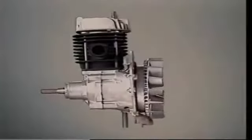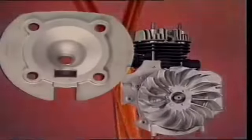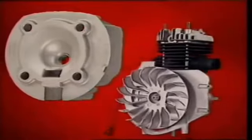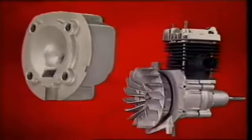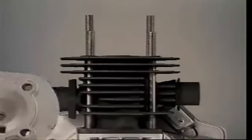In a two-stroke petrol engine, lubrication occurs by mixing oil with the petrol, so oil passages are not needed. And if, like many two-strokes, air cooling is used instead of liquid cooling, there's no need for coolant passages in the cylinder head.